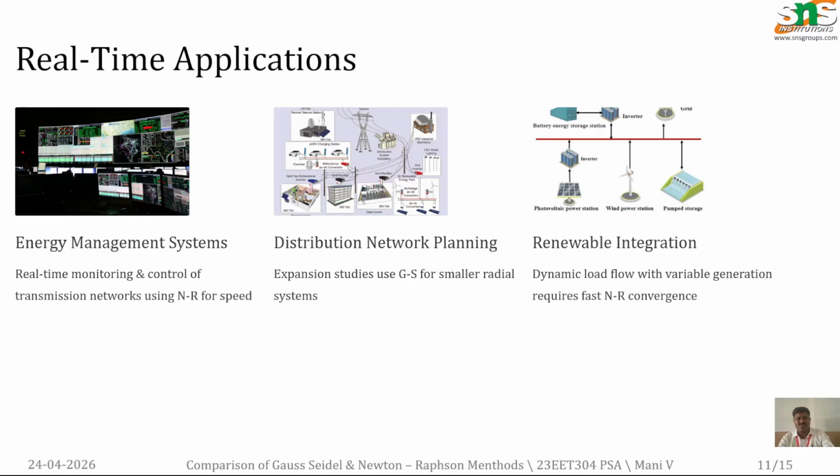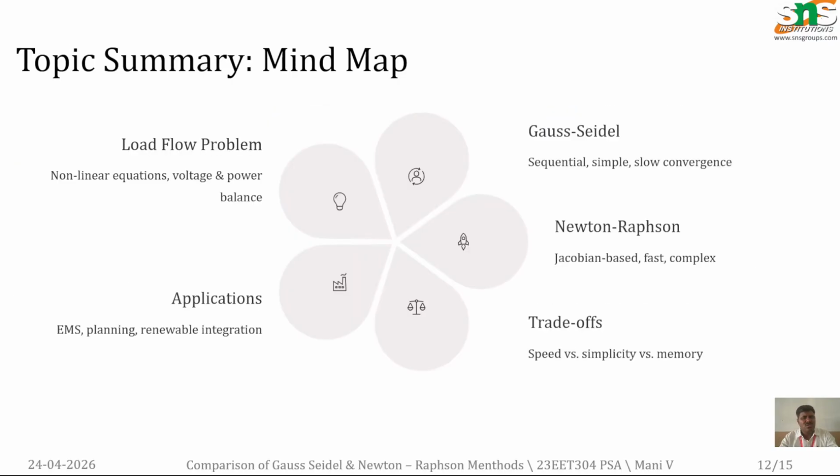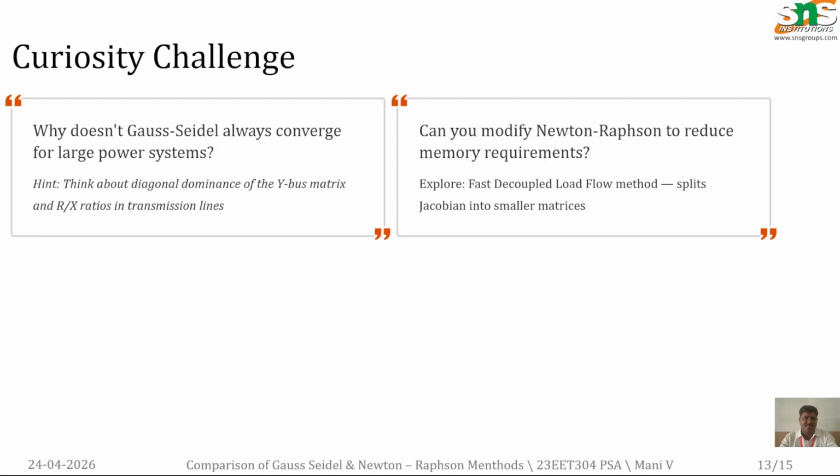This is a real-time application. It can be used in energy management systems along with SCADA, distribution networks, and renewable energy integration. So this is a mind map summary. The load flow problem, whether linear or non-linear, is taken as the input, and we use the Gauss-Seidel and Newton-Raphson methods and compare both on speed, simplicity, memory, and applications.